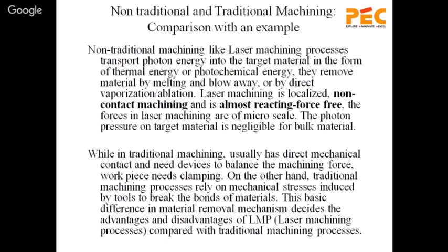Laser machining is localized, non-contact machining, almost force-free, with no heat-affected zone. Forces in laser machining are on a micro scale, but conventional machining is obviously a contact process and has mechanical stress induced in the tool and all this.